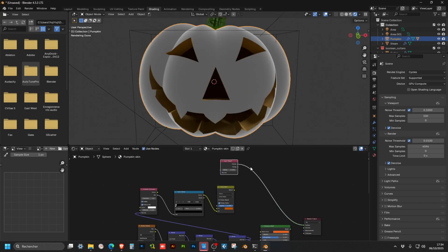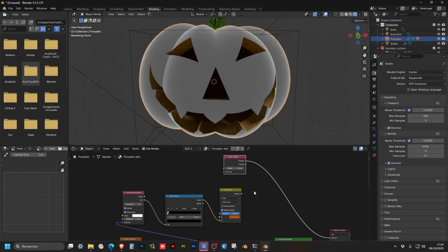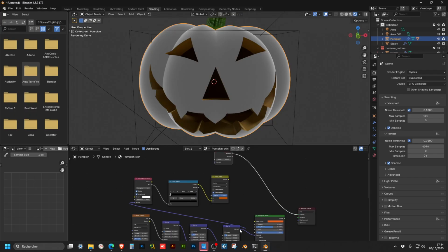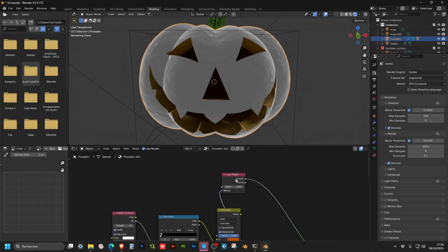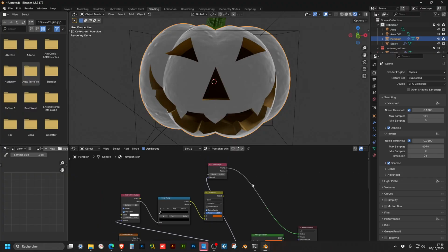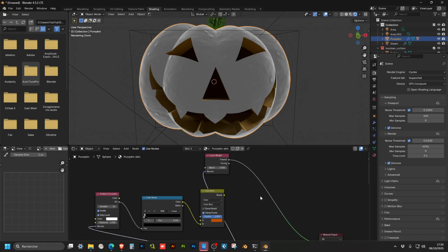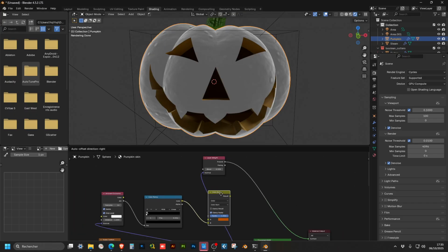The layer weight gives this kind of outside shape like this for the shader. So we can use the normals as well to plug it, and like this it will be even more realistic. So we'll keep the blend like 0.5 and use the Fresnel on top here, and we will mix the outside of this one with another mix one.